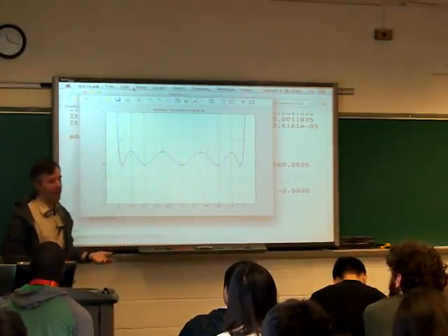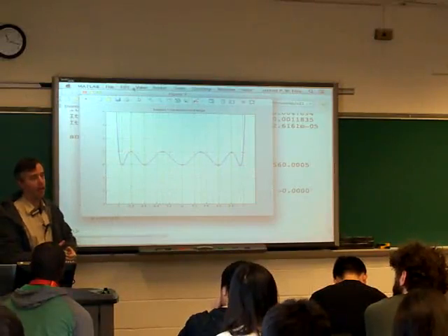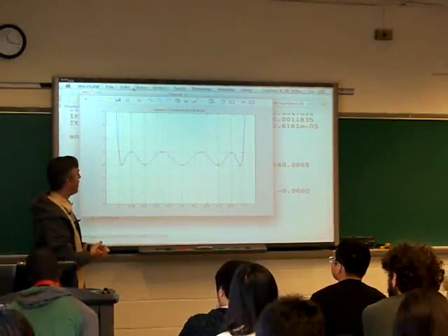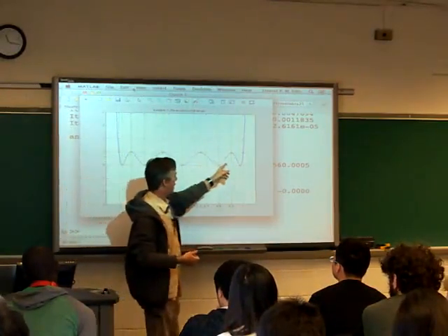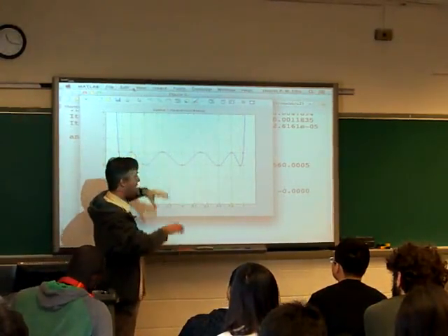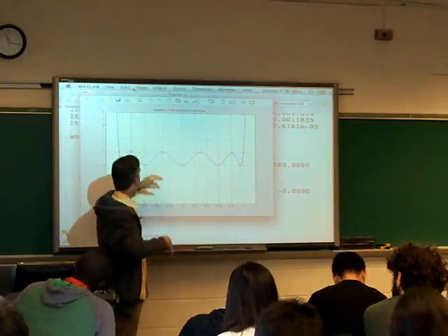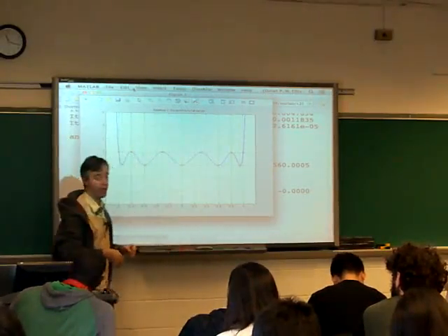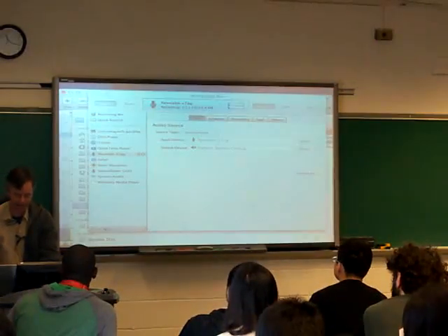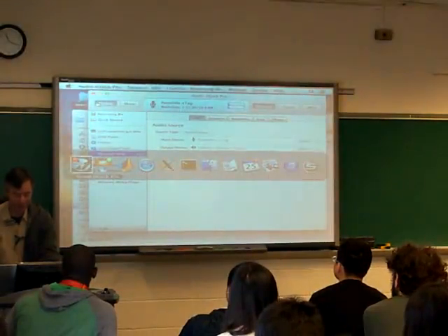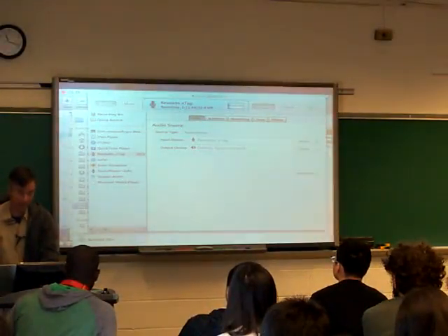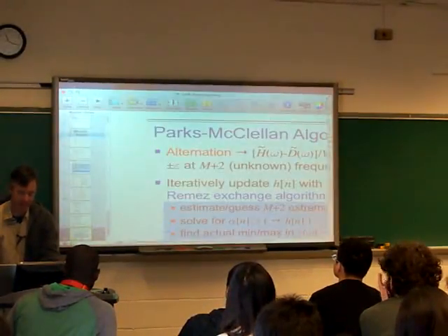And so that's basically the trick that the Remez exchange algorithm, the Parks-McClellan FIR algorithm, is doing to find these polynomials. We can have ripples in different places, can have different shapes, but we'll have equal-sized ripples within each range that we care about. And you can look at the code for that if you want. There's nothing magical about that. The only magical thing is using Lagrange polynomials to fit a polynomial through a set of points, but there's nothing that special about that.